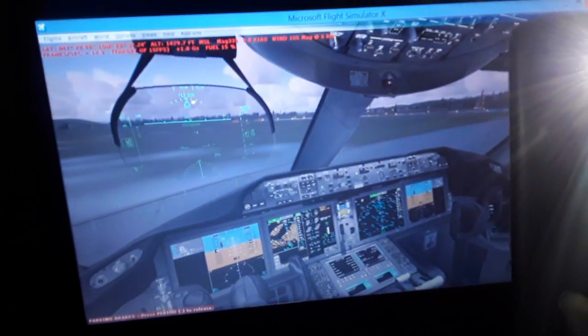Also we're going to be aligned with the LSZH localizer, the horizontal localizer, and the vertical glide slope of the runway. We're going to use again Zurich International Airport LSZH in Switzerland. We're going to receive the runway radio frequency from the antennas of the runway threshold. The aircraft's onboard antennas receive it and will display the localizer with the runway magnetic heading of 136 degrees, for the runway we're going to use for landing. Also the vertical glide slope, we're going to descend using the glide slope.